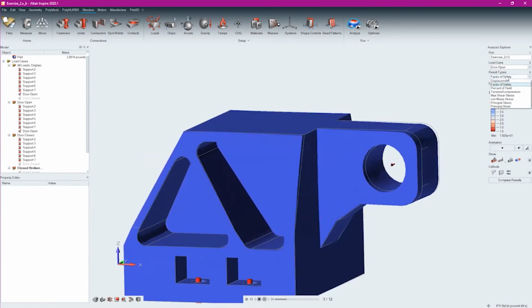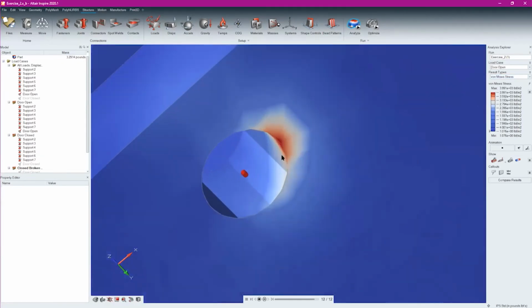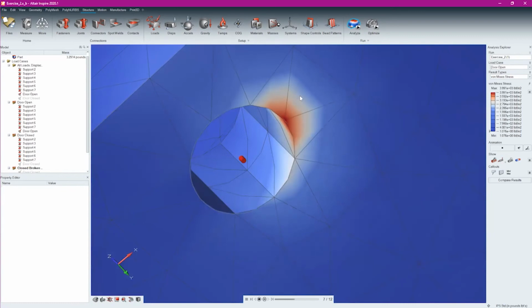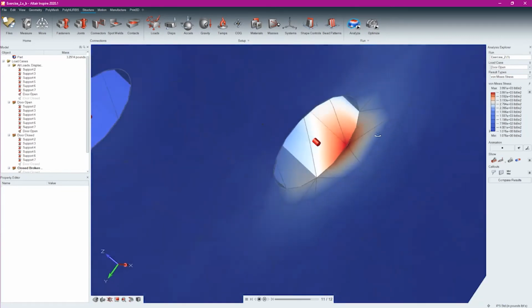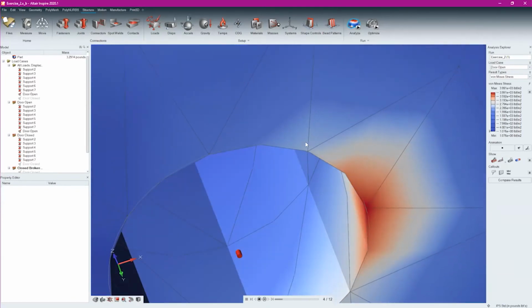Where you're going to see those localized areas is when I look at my von Mises stress, or perhaps at my percent of yield. There I see very, very localized results. This right here is probably, in fact, if I put my elements on, not even stretching across an entire element. That is what we call a point force or a point stress or a stress riser. That's as a result of the geometry and the limitations of the types of elements that we're using. If you see something like this, that's simply because it's resisting movement in that one area, and it's not realistic.